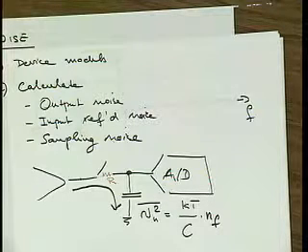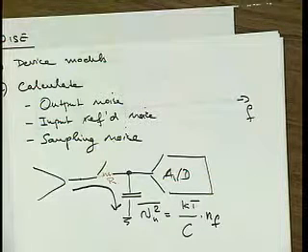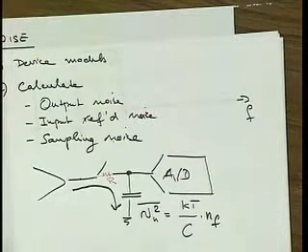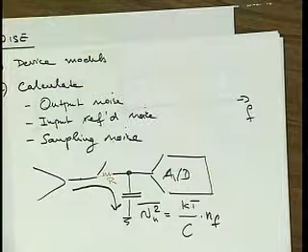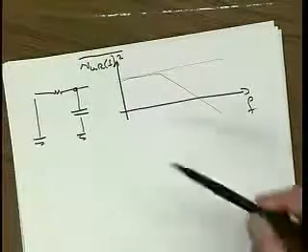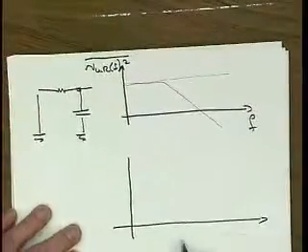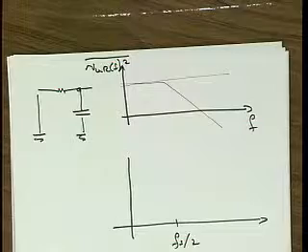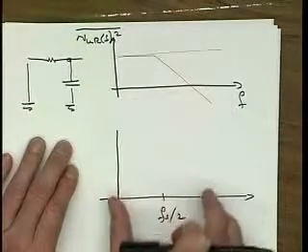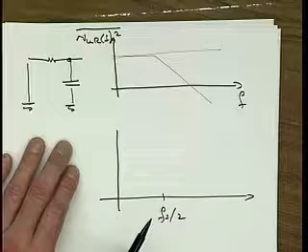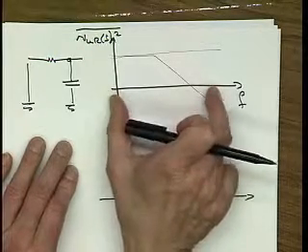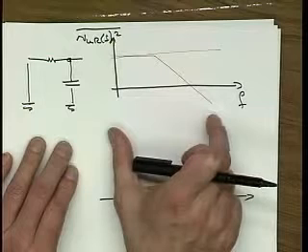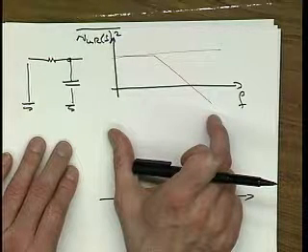Well, first, it's a sampled signal now, so the spectrum is repetitive, or it's defined only from 0 to fs/2, and beyond that it's always the same. So that certainly, for one, is going to happen. But between 0 and fs/2, what is the spectrum going to look like? Well, for that, we need to understand how those noise samples were generated. They were generated from a signal that had this spectrum, the red one here, and then this thing was sampled.